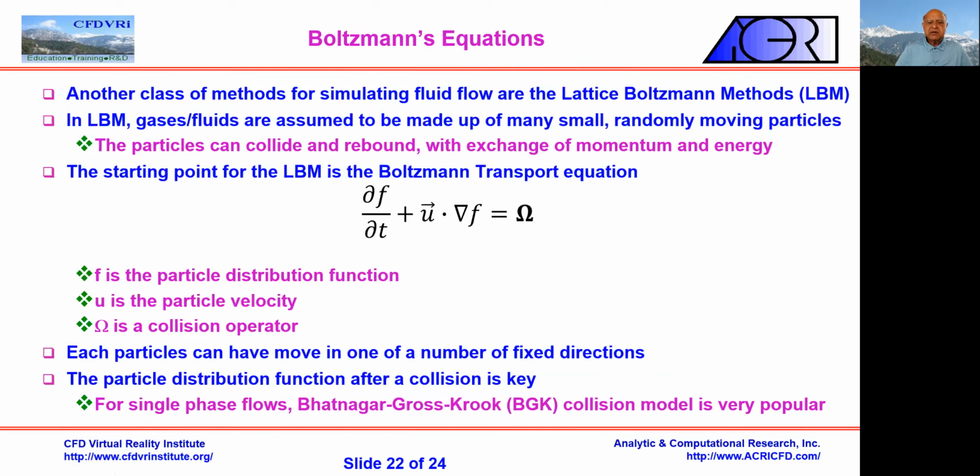The last equation I'm going to talk about is the Boltzmann equation. Actually, this is the most general equation for fluid flow, okay? This can be made to apply to discrete forms of the equation when there are not enough particles present to make a continuum, or it can also be applied when the Knudsen number becomes large and you have very few particles at a point, okay?